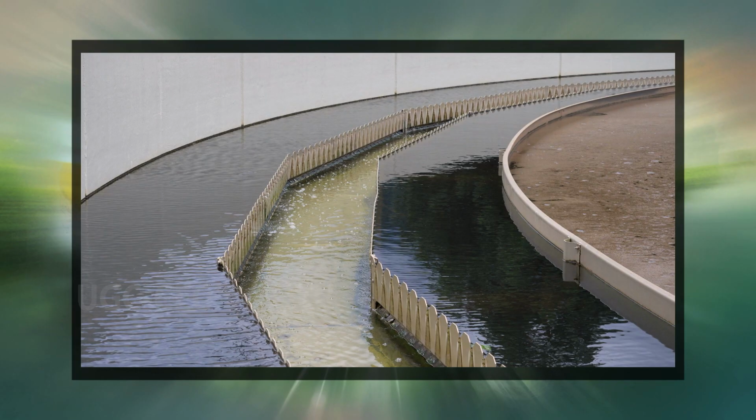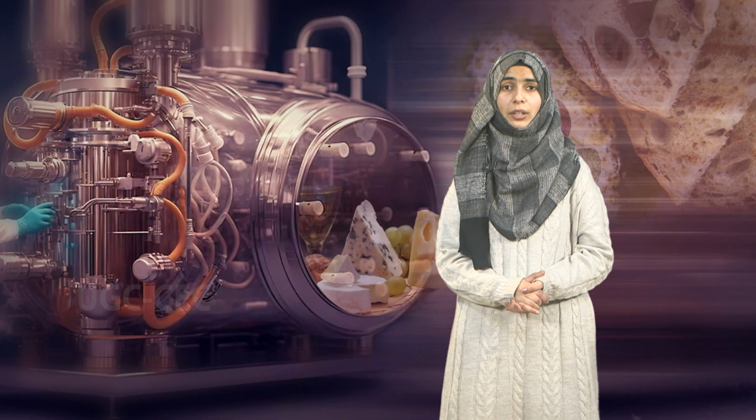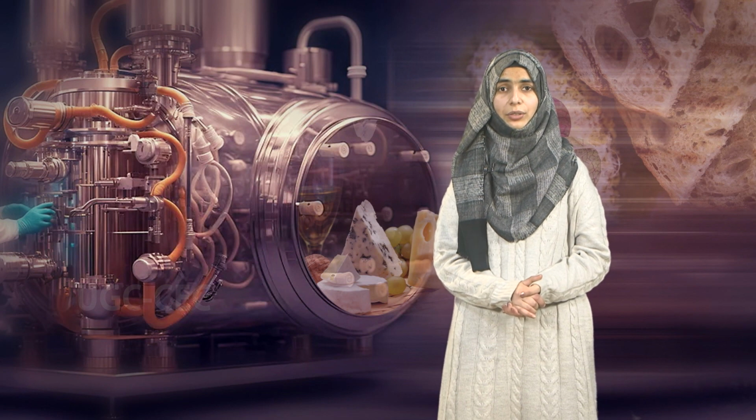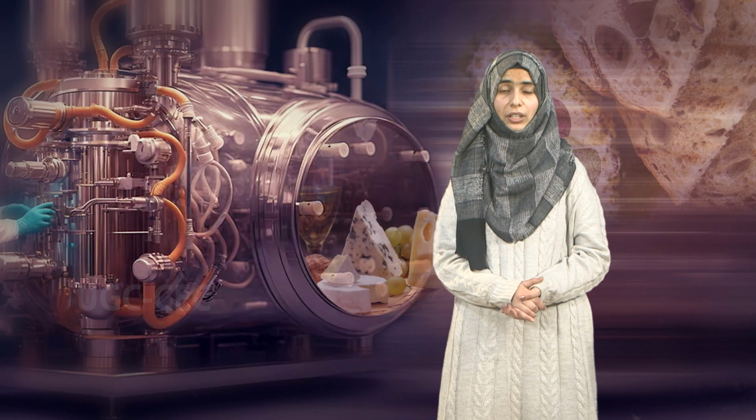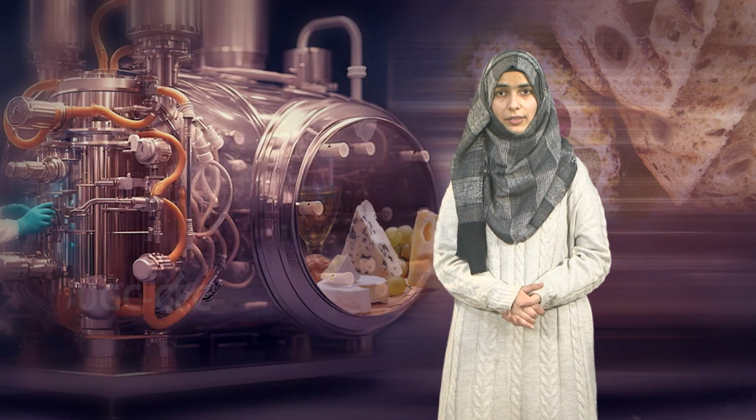Large amounts of organic wastewaters from domestic and industrial sources are routinely treated in aerobic and anaerobic systems. Activated sludge processes are widely used for the oxidative treatment of sewage and other liquid. Such processes use batch or continuous agitated bioreactor systems to increase the entrainment of air to optimize oxidative breakdown of the organic materials.